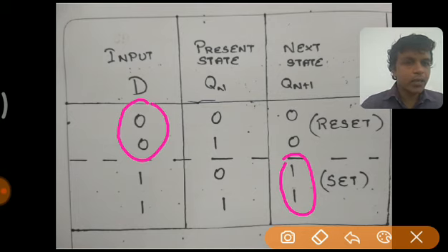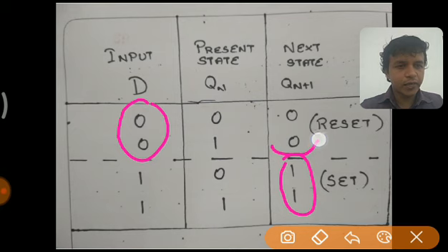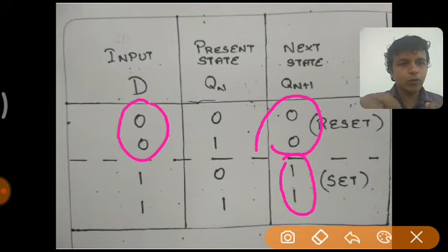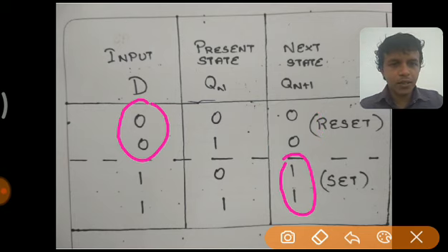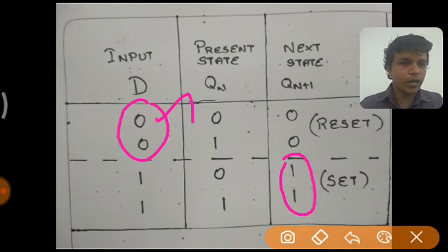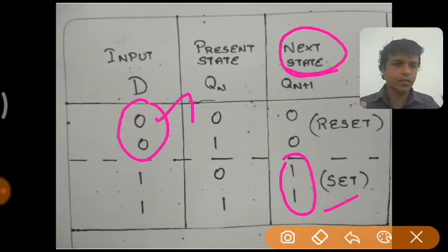Okay, so immediately this flip-flop does not produce 0. What happens, we have to press the clock pulse. Only if the clock pulse is pressed, in the edge triggering portion, it changes its value, and it maintains that value. So if you do not activate that clock pulse, this input does not have any impact on the output of the flip-flop. Output is maintained at the previous state only.